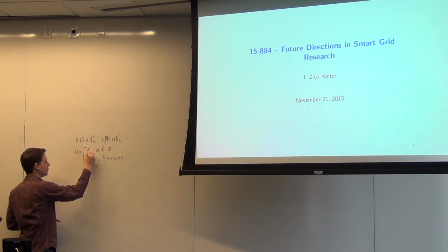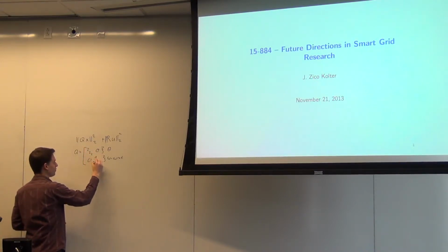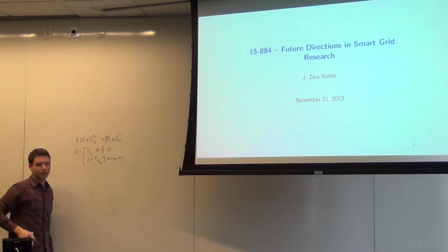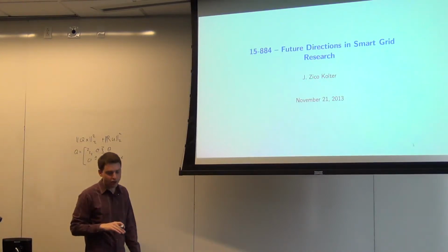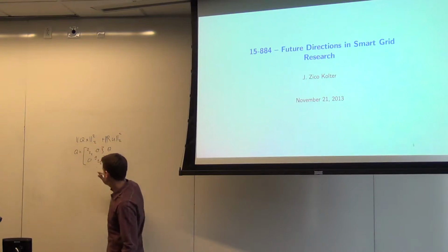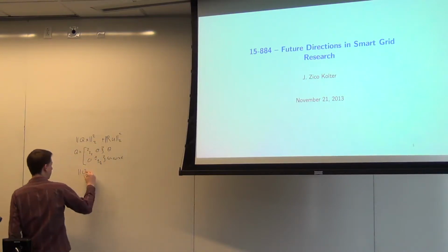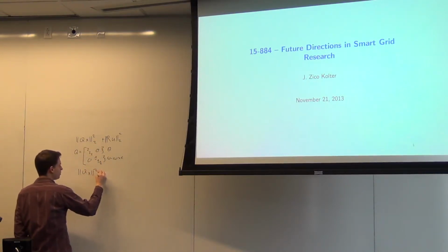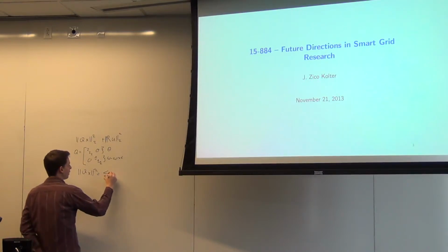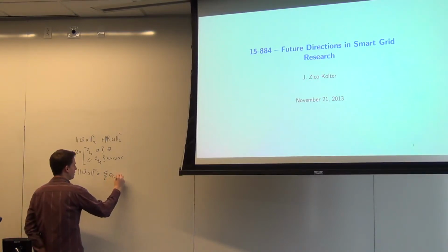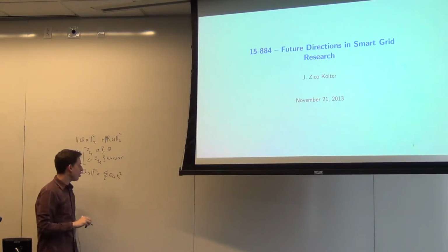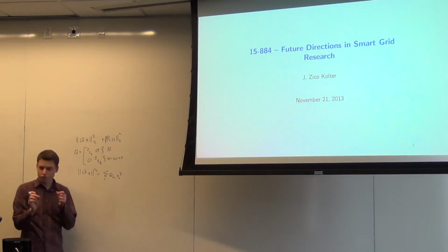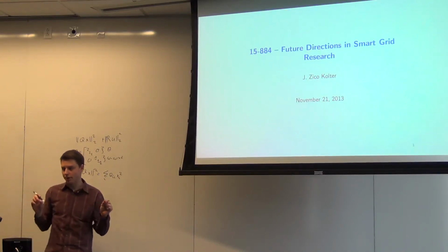I'll make these all 2. I think it's all at 1. Or it's obviously bigger than that, but you have to do the proper sizes. And with a diagonal matrix here, this x transpose Q x is just going to be equal to the sum over all i of q_ii times x_i squared. So all it really is, I'm just weighting each of these functions individually and calling that my cost.